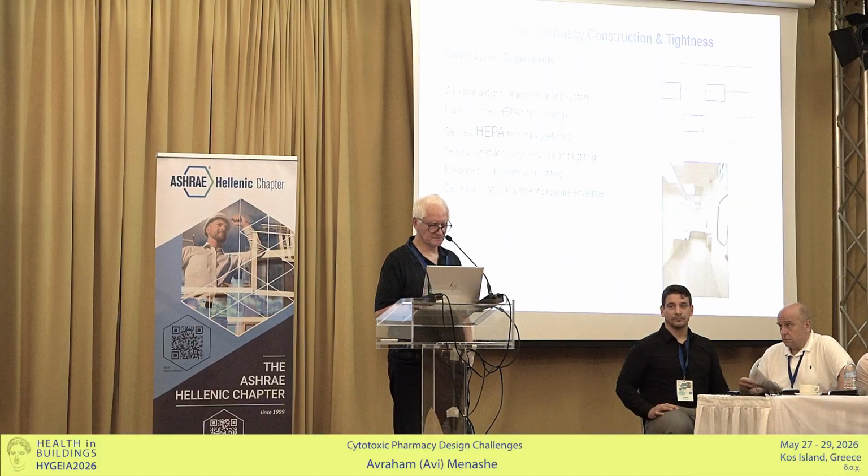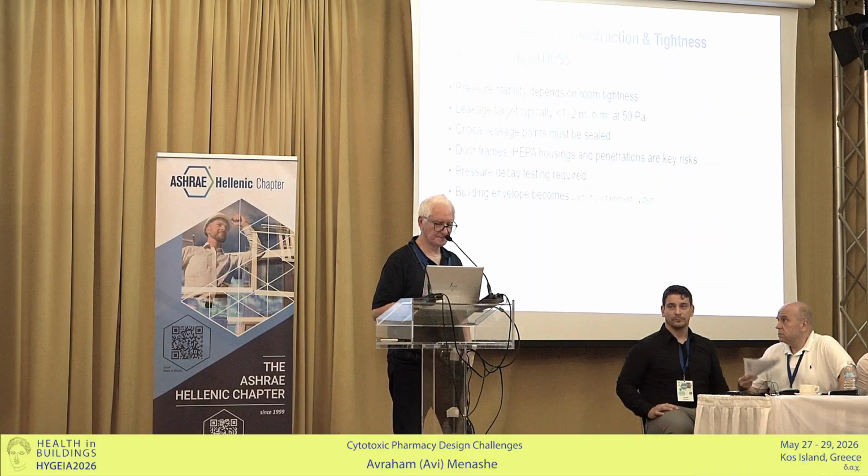The ceiling is also a very important thing, because once you don't keep the ceiling tight, you will have a leakage of air from the plane above the ceiling, and then you lose control. There are typical leakage targets, which are 1 to 2 cubic meters per hour per square meter at 50 Pascal pressure.